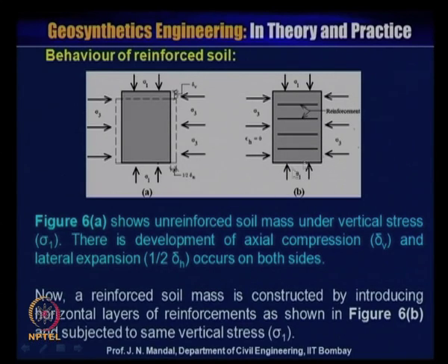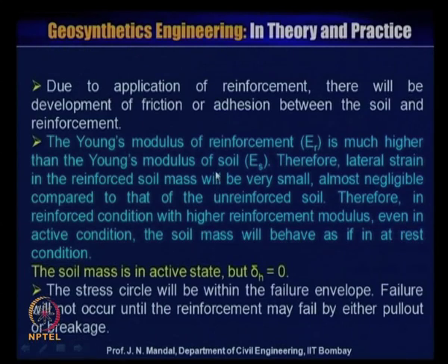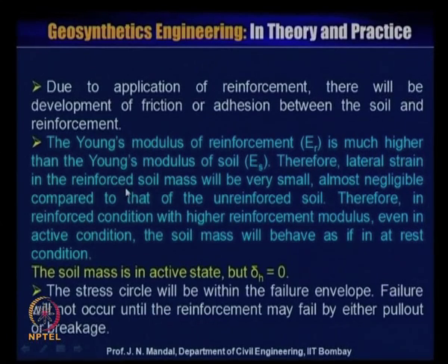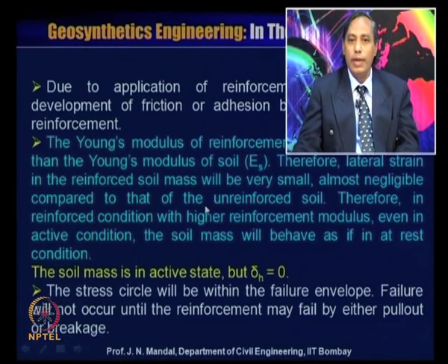So, we wanted to study why it is 0. Due to application of the reinforcement, there will be development of friction or adhesion between the soil and the reinforcement. Now, every material has a Young modulus. The Young modulus of the reinforcement here is much higher than the Young modulus of soil. Therefore, lateral strain in the reinforced soil mass will be very small, almost negligible compared to that of the unreinforced soil.